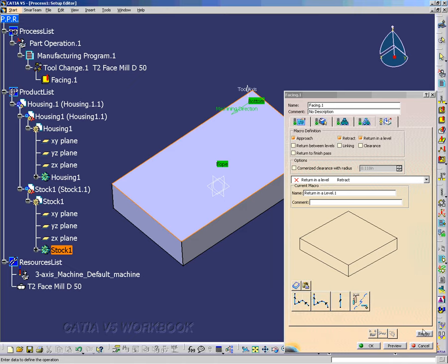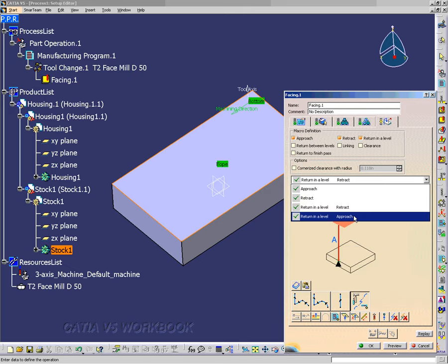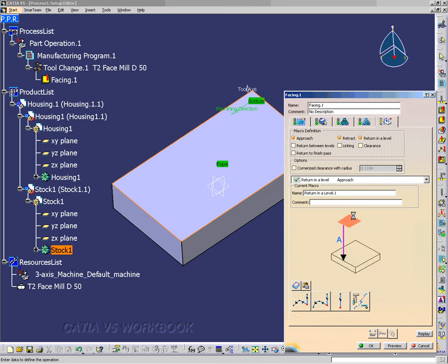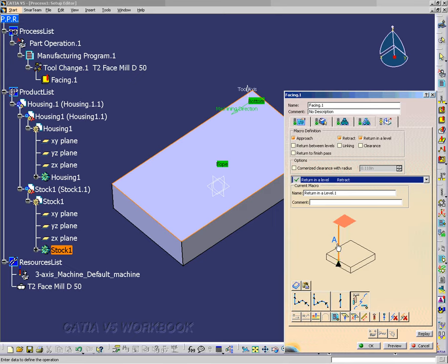I'll just cancel that. That just shows you what you can paste. And I'll add an axial motion up to a plane. And I'll right click feed rate, and I'll go rapid again. And just to double check, I'll have rapid there. So everything looks okay.